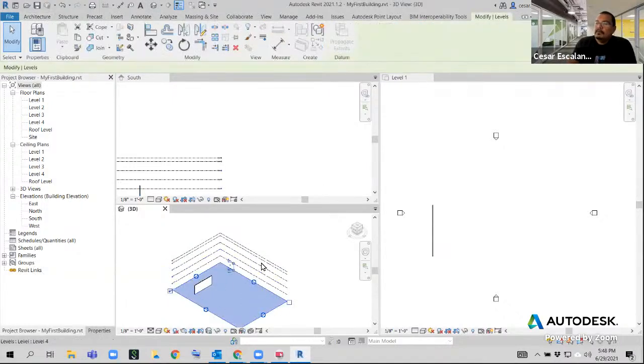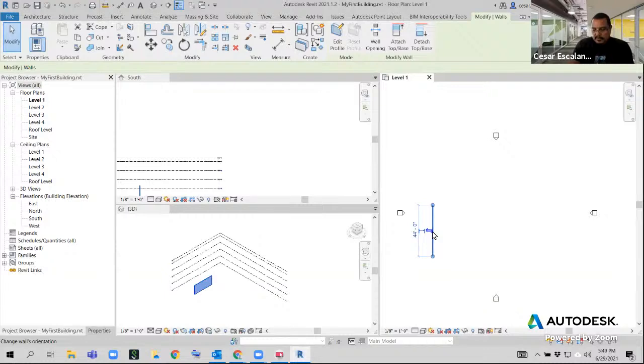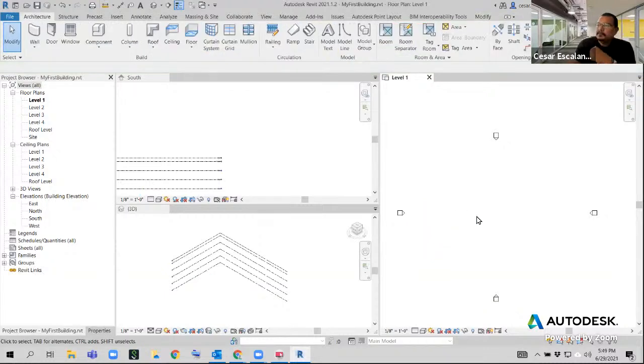And so when we select a grid, notice also that there is a way to modify and create levels. This is the contextual tab, and the contextual tab disappears after you deselect an object. So I click escape, and now the contextual tab is gone. I'm going to delete this wall. So that was just an example.